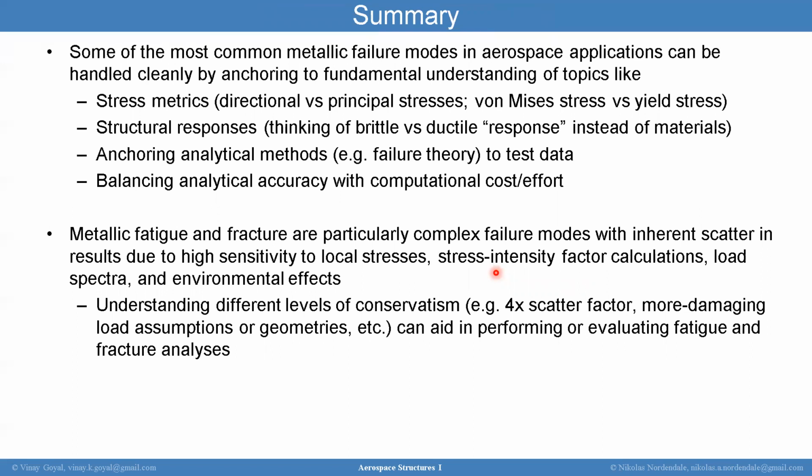So, in summary, most of the metallic failures in aerospace applications can be handled by anchoring to a fundamental understanding of topics like stress metrics, stress responses, anchoring analytical models, and balancing analytical accuracy with computational cost and effort. Also, metallic fatigue and fracture are particularly complex failure modes with inherent scatter in results, and that's why I use a 4x scatter factor. For high cycle fatigue, some people even use 10x.